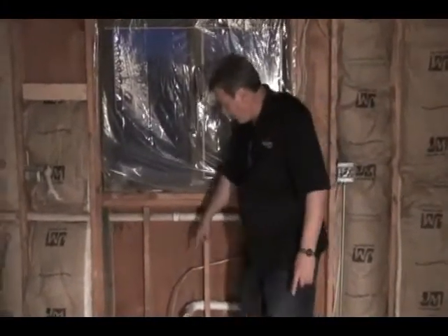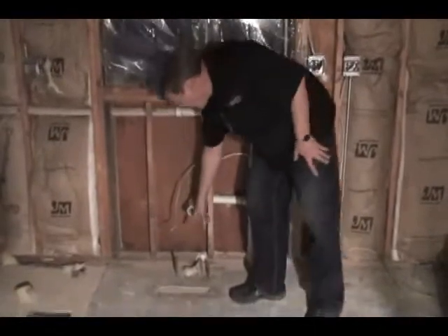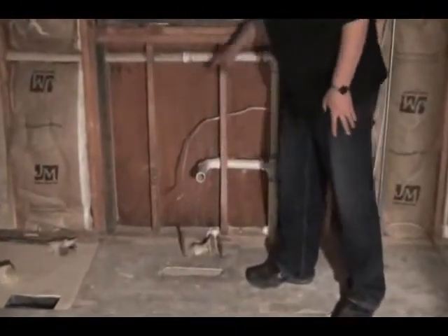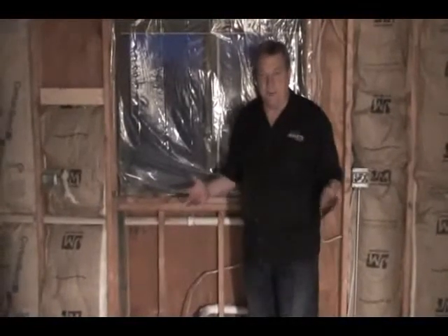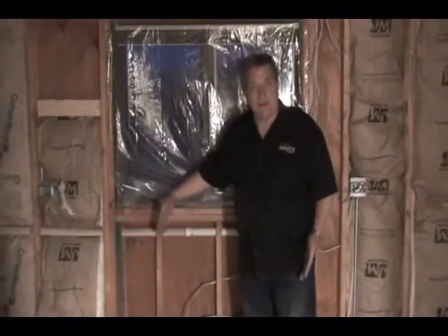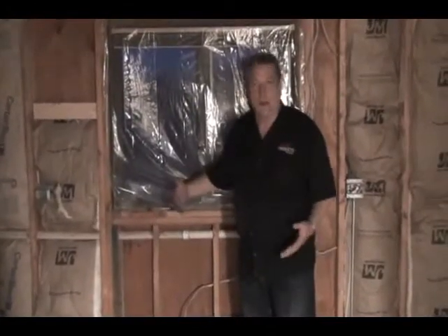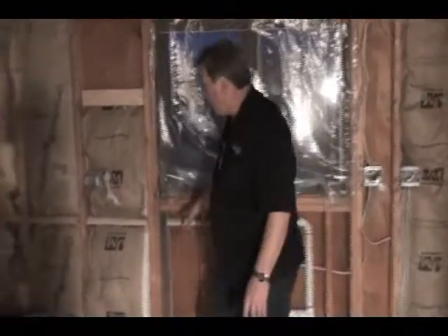We can also put another one here where the sink drain's at. You notice down here there's 2 copper pipes coming up. We can hit 2 points here and indicate where the copper's at. If I was in the cabinet business, this would tell me where the sink needs to be in relation to the size of the base units, whether it's custom or stock. Moving around, this would be just each stud.